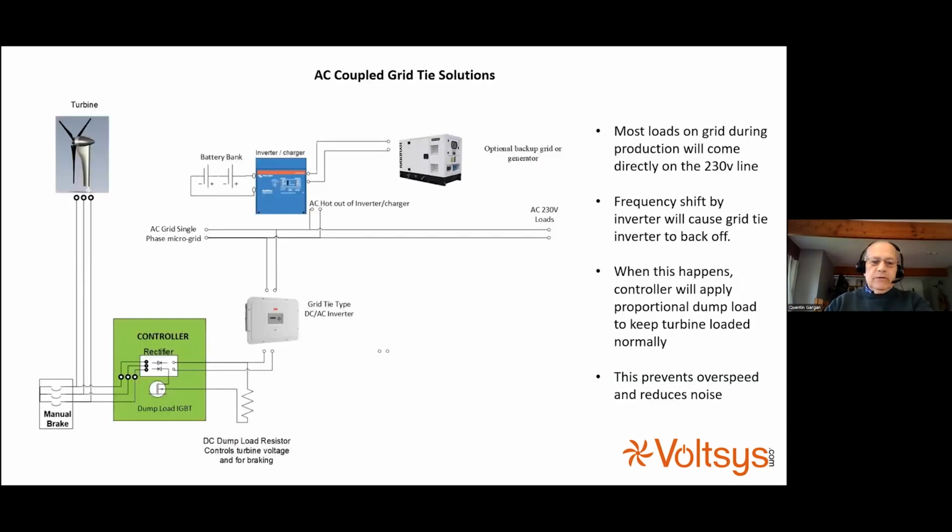For off-grid applications, rather than putting the turbine directly into the battery, as in an awful lot of older off-grid applications, where the turbine was put into a battery, the MPPT tracking for the turbine was not observed. The turbine spun freely until it got to battery voltage, and then it was locked to that battery voltage, working basically the same way that an asynchronous turbine would work. It was fixed to a fixed speed almost.